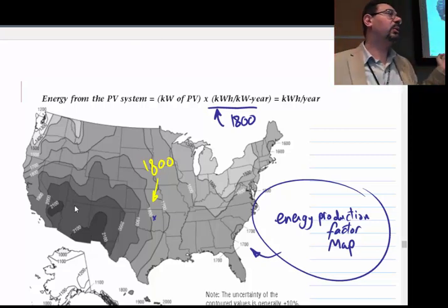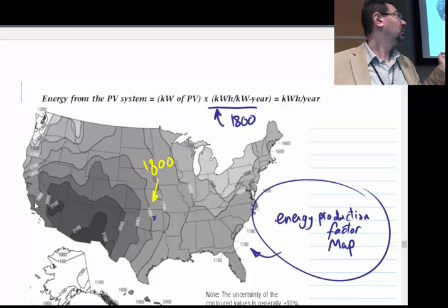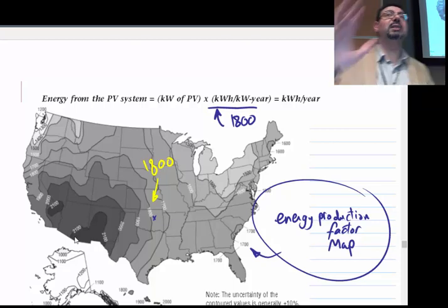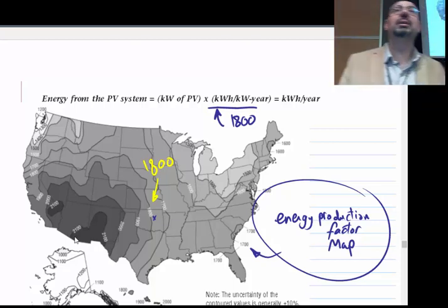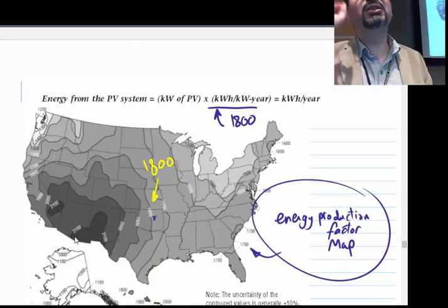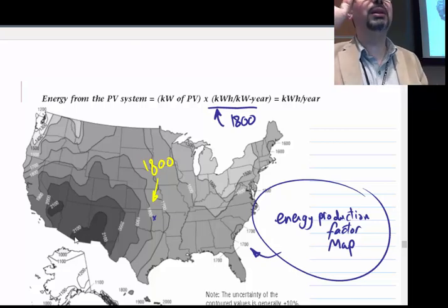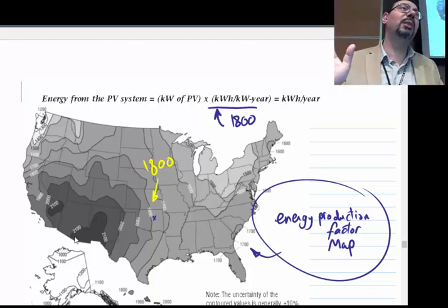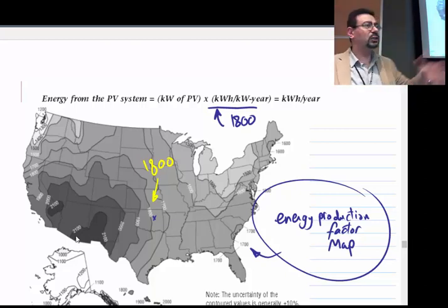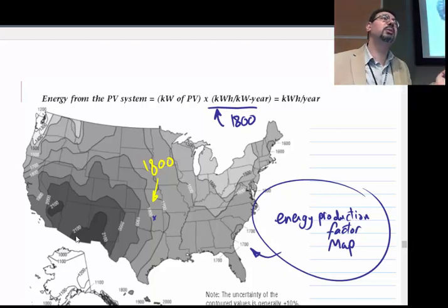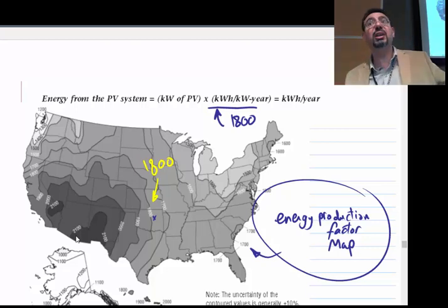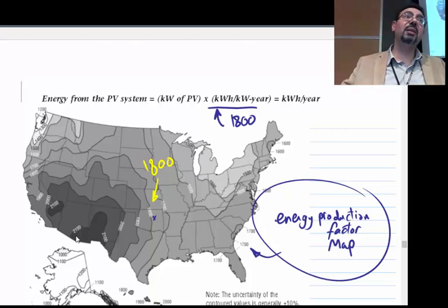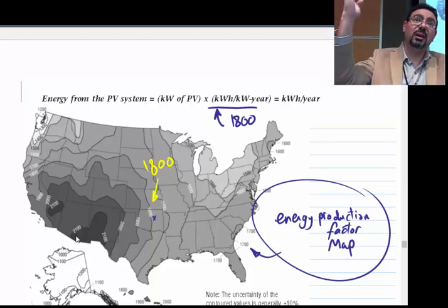What is the maximum hour per year we should expect? What is the maximum power we should expect? What is our Carnot cycle equivalent of hours? We cannot get 8,000 because there is night. We cannot ignore the fact there is night. But at least half the day is like the maximum you can imagine. So let's call it 4,000. So 4,000 is the maximum possible of one sun. And it's super hard because part of the day the sun is really low, so you have to give the sun some time until it really heats up. Right? That was one question.